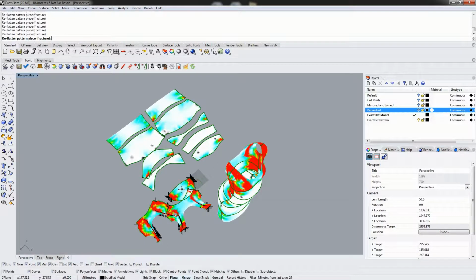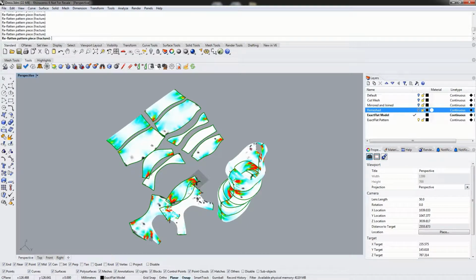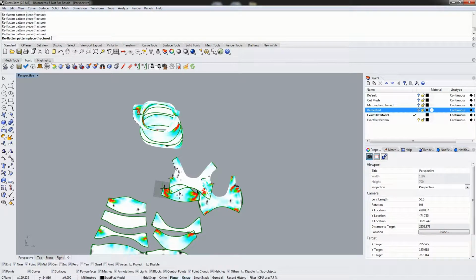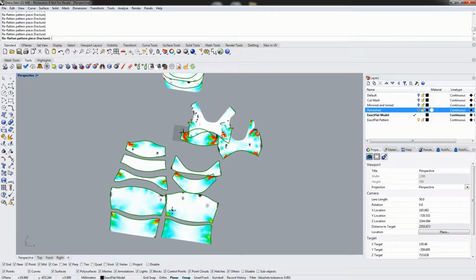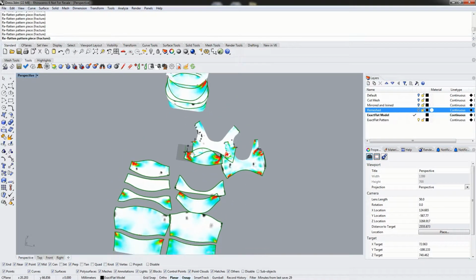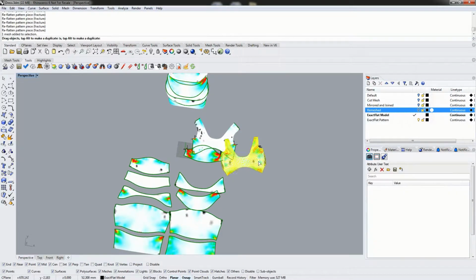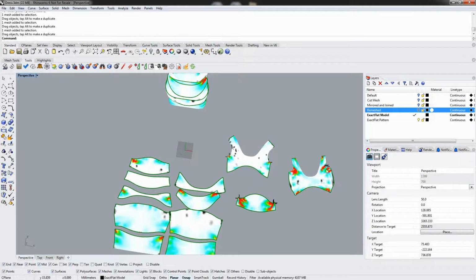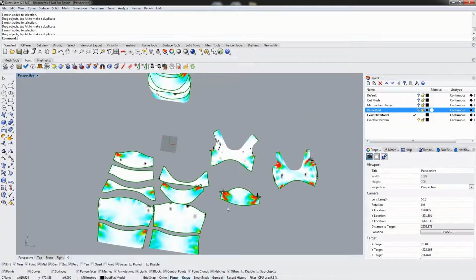But with fracture, we're using fracture because these pattern pieces are symmetrical, so we want to try to preserve the symmetrical shape of the pattern pieces, and we're also using fracture because it tends to give very good results with these shapes here. In the case of these pieces here, just going to drag these away. And even this one up here, we do have some folds and wrinkles or flip triangles. So fracture did not work on these ones.